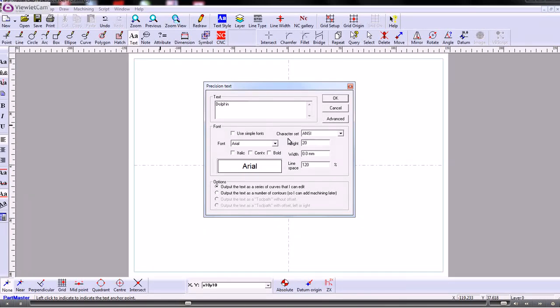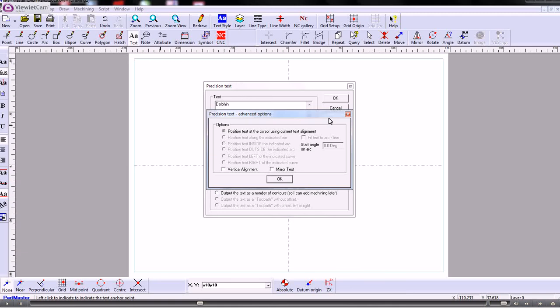If you're fitting text around any existing item along a line or around an arc or around a circle and so on, then you need to go to the Advanced tab here and then select the options available. Depending on whether the indicated position is part of an existing element, a line, an arc or something like that, then these options here will become available to you. The one to watch out for is this one, fit text to line arc. In some cases that will automatically be checked, and that may or may not be what you want.